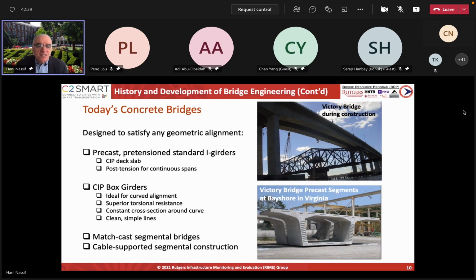However, in many cases now we are realizing that for a steel tendon, that is an issue because there is water infiltration, sometimes even in the grout. And about maybe 10 years ago, it was found that some of the grout had very high percentages of chloride in it. And then it was attacking the tendon, and a lot of the tendons were getting corroded because of that.